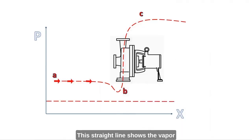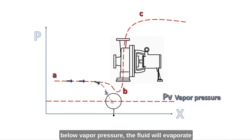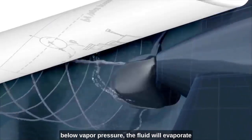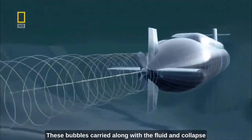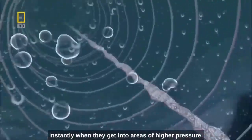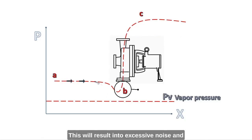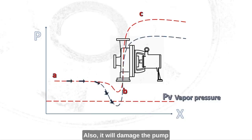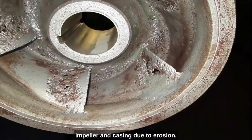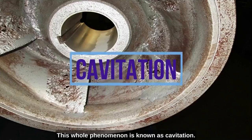This straight line shows the vapor pressure corresponding to the fluid temperature. If the pressure at pump inlet drops below vapor pressure, the fluid will evaporate and generate small vapor bubbles. These bubbles are carried along with the fluid and collapse instantly when they get into areas of higher pressure. This will result in excessive noise and vibration due to collapse of vapor bubbles. Also, it will damage the pump impeller and casing due to erosion. This whole phenomenon is known as cavitation.